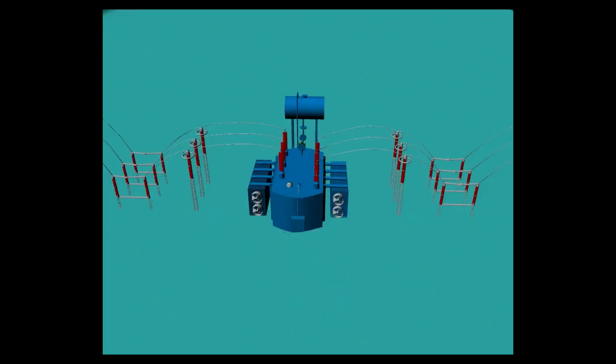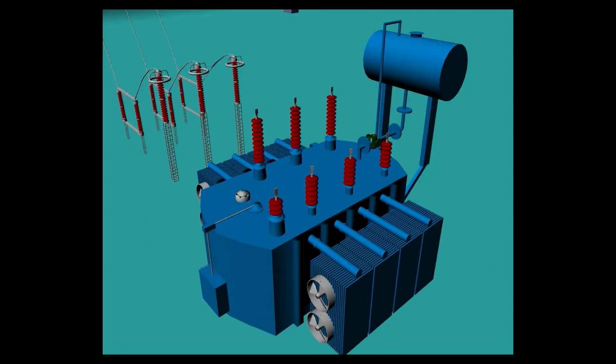First of all, isolate and de-energize the transformer. Then short all the HV windings and neutral if any together. Then short all the LV windings and neutral together. Note the oil temperature because the insulation resistance value is highly dependent on temperature, and insulation resistance readings are corrected to 20 degrees Celsius temperature.